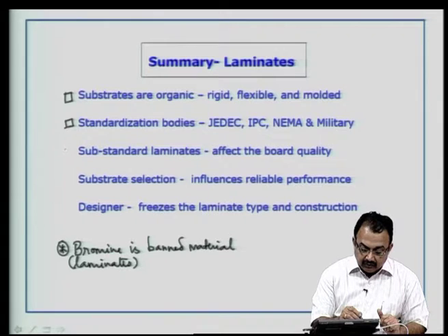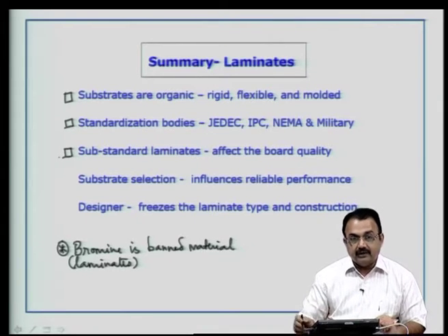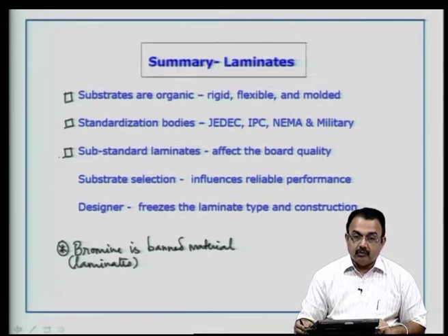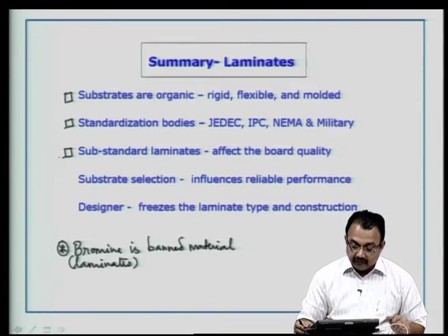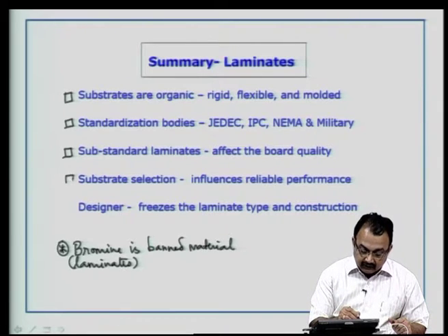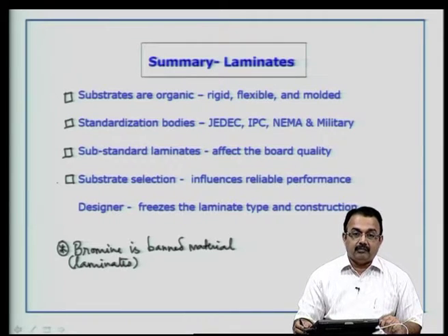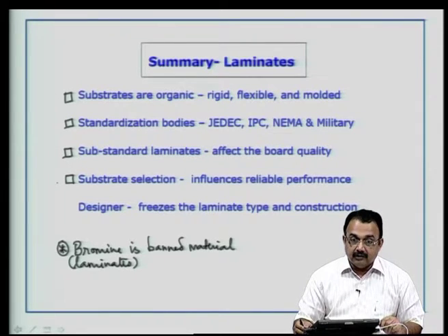Then do not use substandard laminates. Electrically they are going to affect the board quality, thermomechanically also they will affect the board reliability. Substrate selection, as a designer, spend a lot of time in understanding what a substrate is, because it influences the performance of the board, especially in high frequency applications, high performance applications and strategic applications.